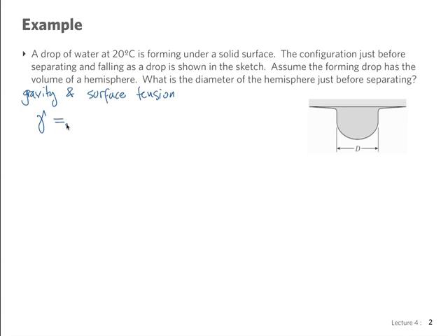I have it right here, so we save a little time today, but you would have to look this up. In fact, this number you could even get to learn by heart. The specific weight of water at standard conditions is 9,790 Newton per cubic meter. And the surface tension, 0.073 Newton divided by meter. Remember, it is force per unit length. And this is at 20 degrees Celsius. Okay, so we have all the properties that we need.